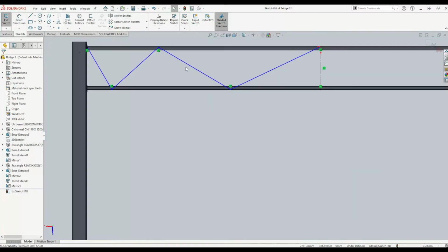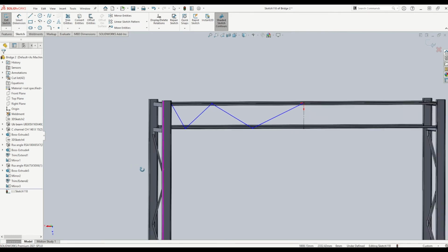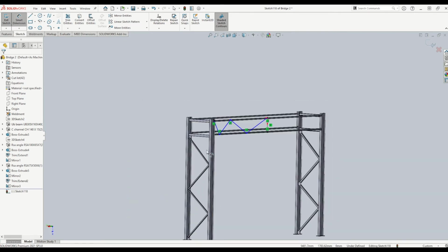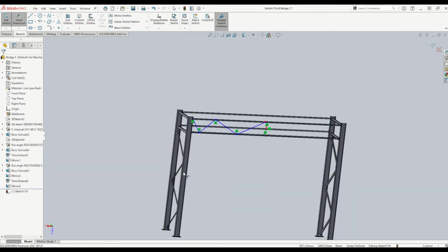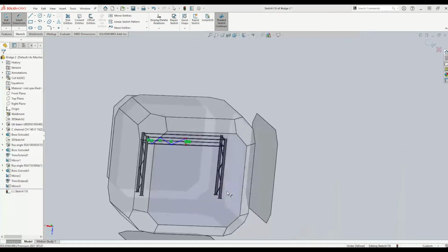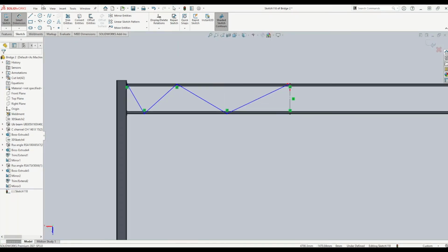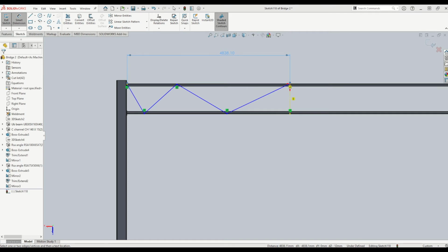So the best way to do this, if you're watching the first video, I parametrically modeled this with equations. So if you change the height of your 3D sketch, it all changes with your size changes, and it all parametrically changes. So what I'm going to do is something similar here. I'm going to draw a smart dimension from that point to the center line, and it should come up, which it has done: would you like to make this dimension driven?